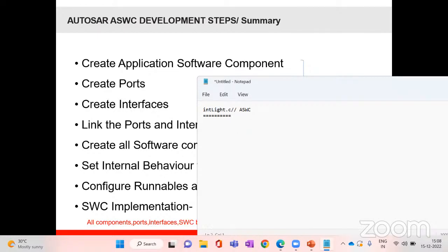Okay. So now we will talk about, after we create this thing, the next ideas. We would have created data types. We would have created data sets, and in data types we have both implementation and AUTOSAR data types. Of course, this could also be mapped with application data types. Application data types are mapped with implementation data types, which in turn are mapped to AUTOSAR data types. So once we have this done, we create port interfaces.